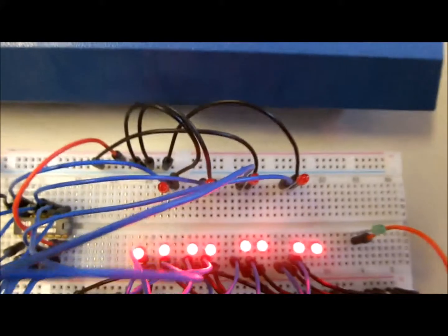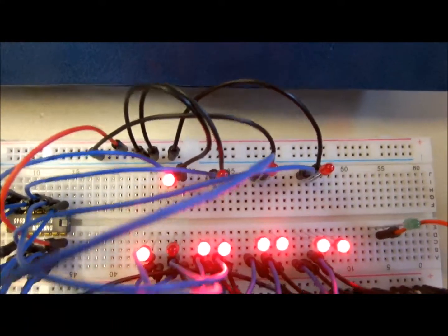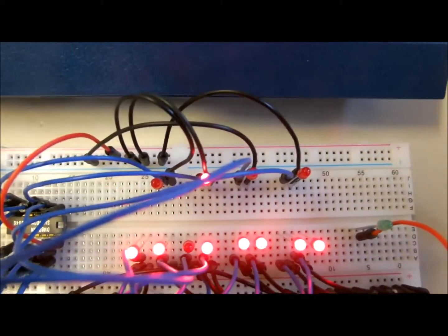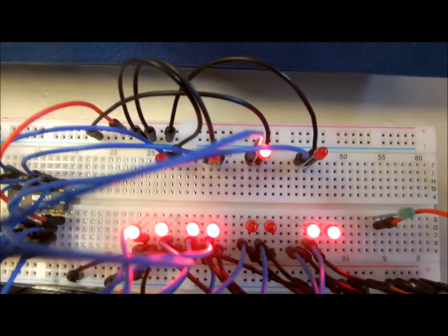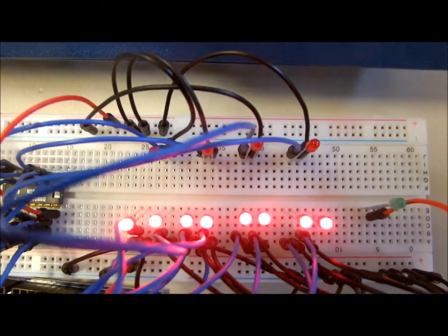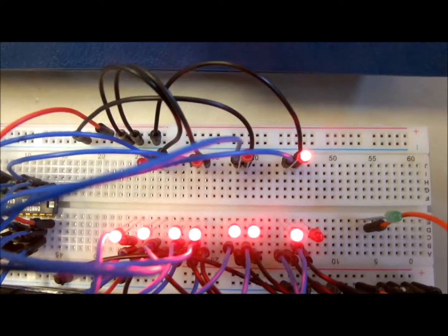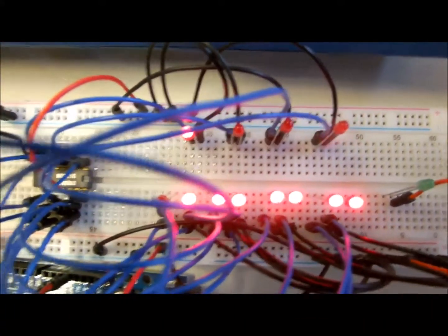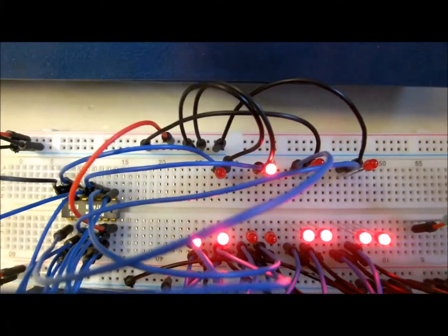And over here on the LEDs, you can see as it goes through the gates one at a time. I've got it going with about a 1.5 second pause between each transition of the input gates. You can see we're on gate 3 now. And when we go to gate 4, you'll see the output is on, both off input, one on input, the other one on, both on, and the output goes off again. Then we go back to pin 1. So you can watch each gate get tested.